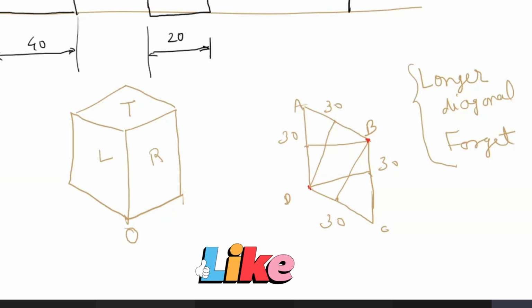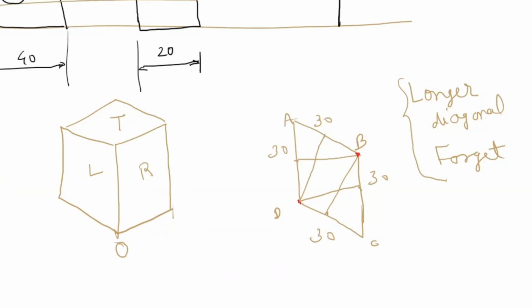Now for drawing the ellipse, one center will be this, the second center point will be this. How many center points have I marked here in green? Two center points marked in green, and at the same time two center points marked in red. So if this is the center point, B is the center. How many center points can you see? Four. Two are at the corners of the shorter diagonal, and two are formed by the intersection of these lines.